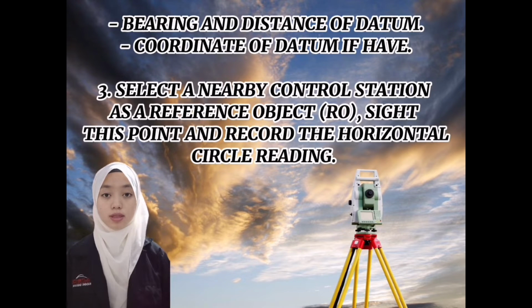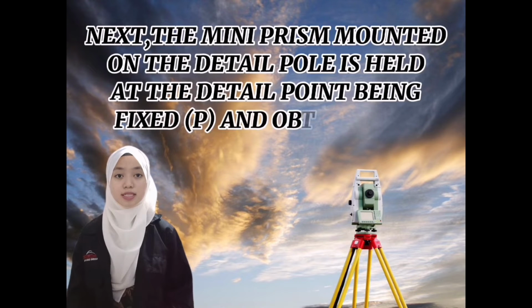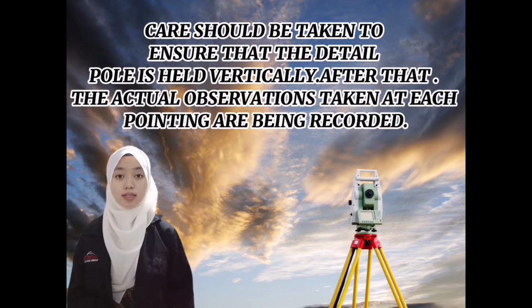Third, the procedure. Select a nearby control station as a reference object. Sight this point and record the horizontal circle reading. All the details in the radiation pattern will now be fixed in relation to this chosen reference object. Next, the mini prism mounted on the detail pole is held at the detail point being fixed, P, and observed by the data station. Care should be taken to ensure that the detail pole is held vertically.